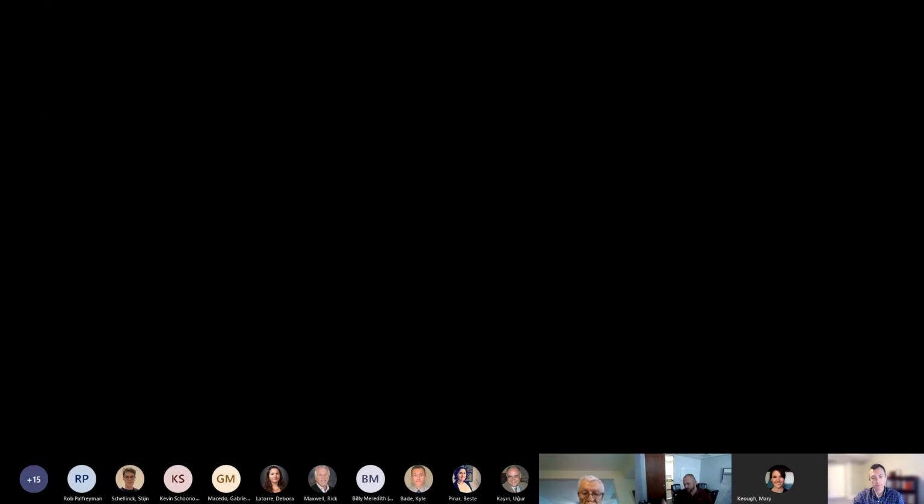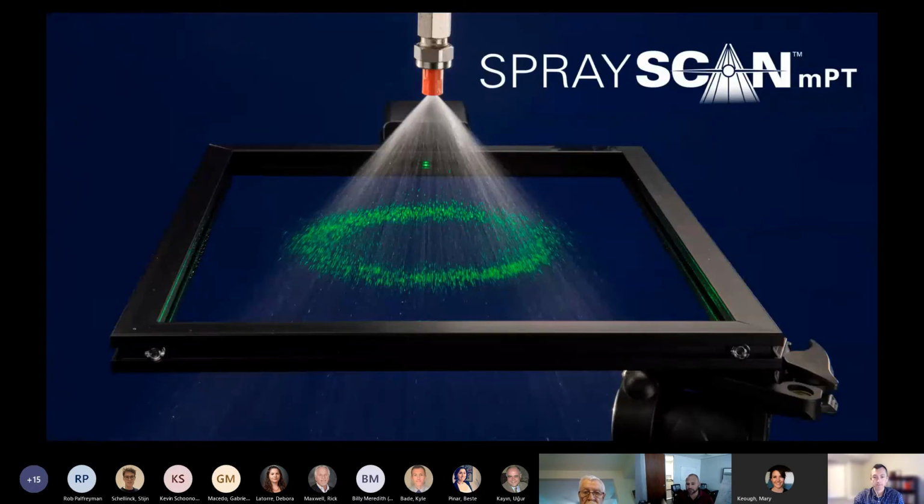Yeah, that's pretty important. You know, oftentimes in various processes, we see, let's say it's at a plant or for a turnaround, folks will take out a nozzle and they'll say, oh, look at that, it sprays. You know, visually, the human eye has difficulty discerning, even with the flow rates increasing more than 30%. So imagine how much more wear and tear on that one nozzle you're going to create for your upstream and downstream processes, upstream being the pumps, downstream being the flow rates that might be happening along with the larger drop sizes, increased impingement, et cetera.